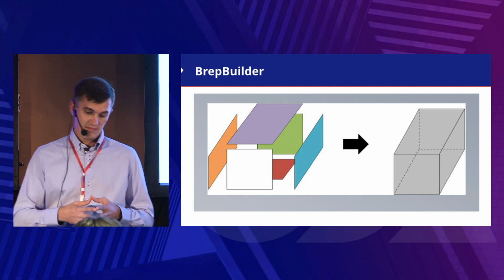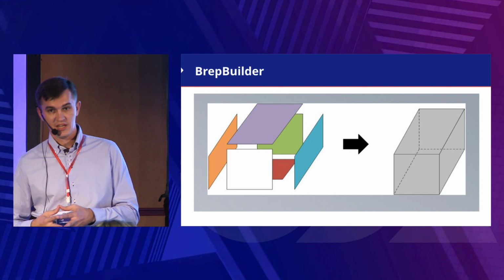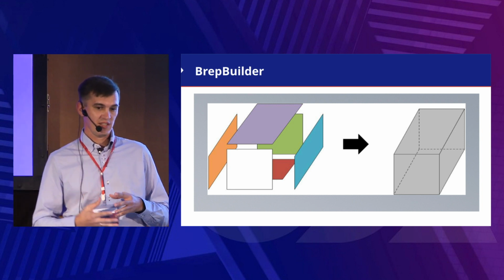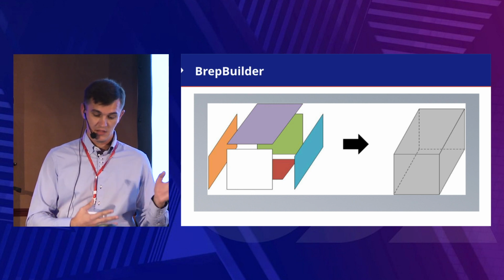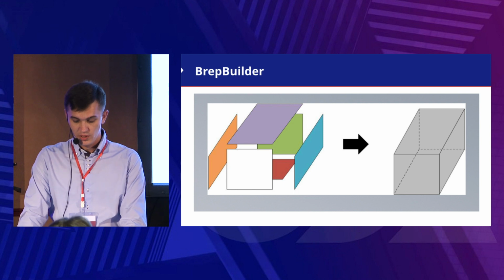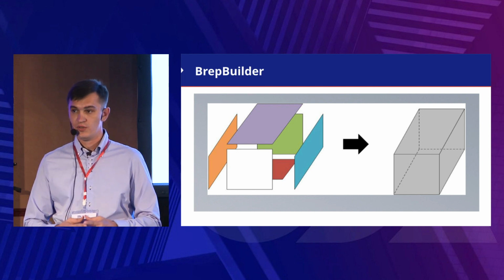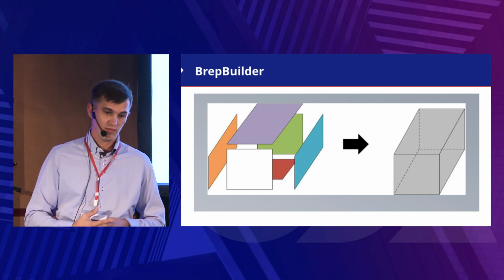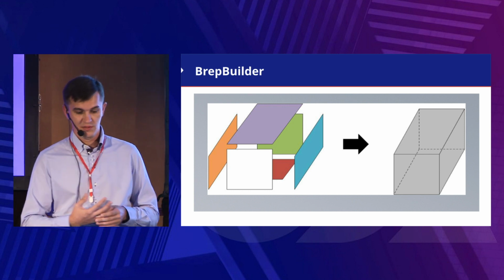So the customer should fill the BREP builder with the faces, edges, and their relations, and in the end, the BREP builder must create correct BREP data for the file format. This currently works for BIM. We actively use it for creating our internal BREP representation, and this can also be used for creating BREP data for direct shape, for example.